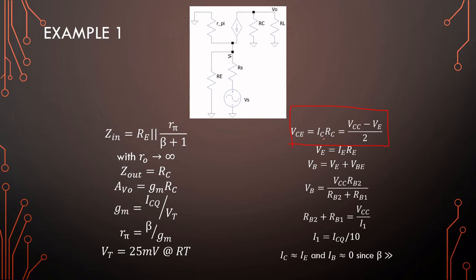So this one is even applicable for the VCC over 3 case. But typically with the R load prime approach, we are going to have a different VE value. Okay, so VE's value, VB's value, VB is a voltage divider, and the rule of thumb. So these are all the equations or adaptations that we are going to use in this problem.